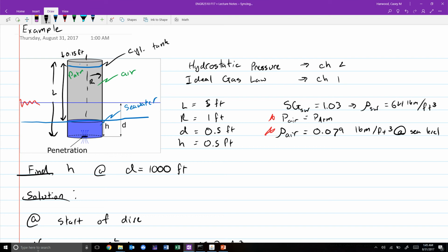So for example, if it's air valve, or if it's air tank that it uses in order to blow air back into this and drive the water level back down to cause it to rise, and there's a clog in this line or something blocks this compressed air line, this probe is gone. It does not self-recover. It does not find an equilibrium and hang out in a neutrally buoyant position. It's an unstable system. It's going to continue to sink, and its tendency to sink is only going to get more and more pronounced as it goes deeper.